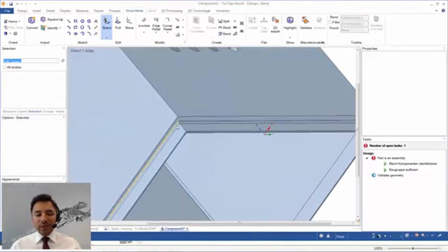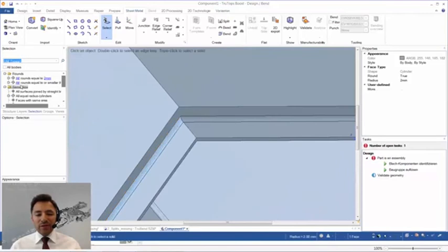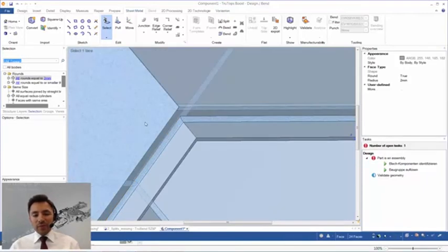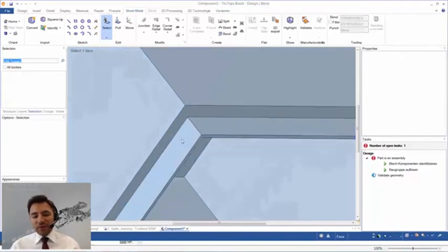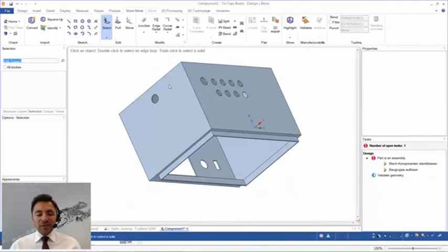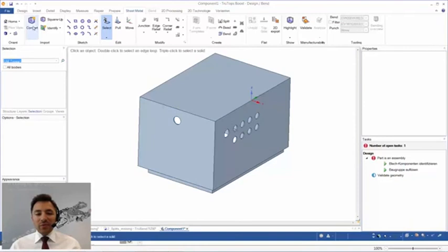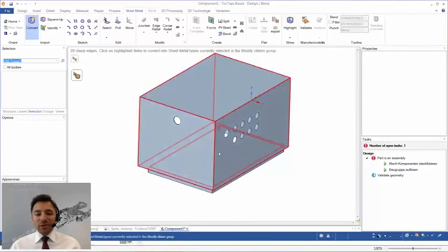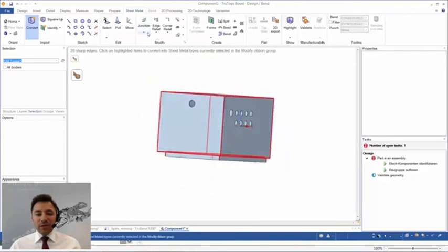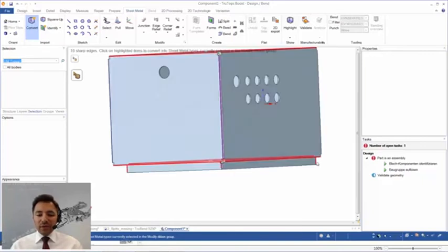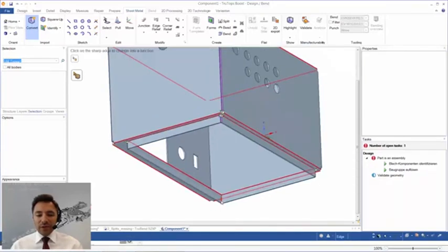in order to get sharp edges, and fill also that radius. So with the power selection tool, I have selected all the radiuses with a few clicks, and what I do now is I just convert that bulk and assign no overlap to those 4 sides, box select from right to left, and also those 4 edges at the bottom.